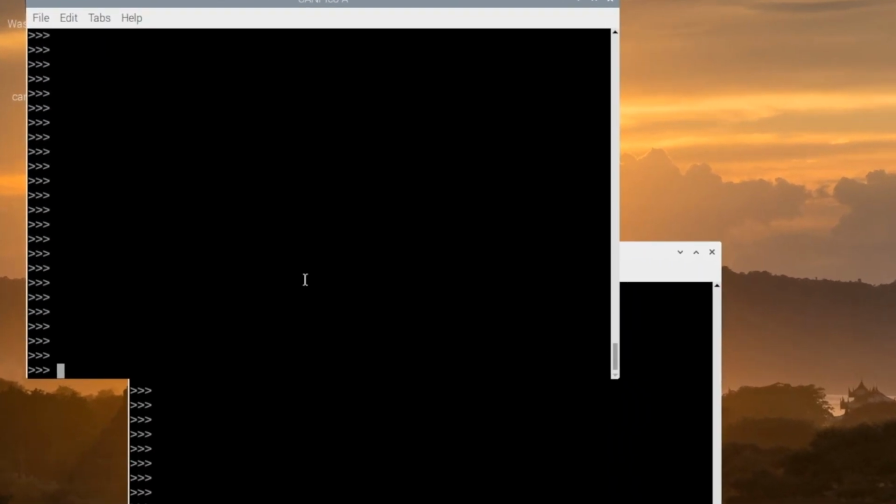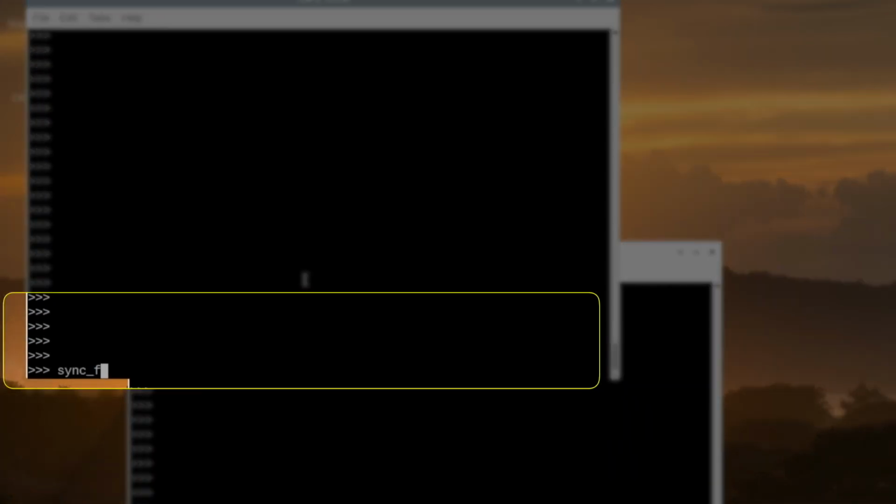So what we have is a pair of sync frames. The first sync frame is just a simple short CAN frame with ID 0, no payload. And when the other side receives that frame, it queues its own CAN frame through the drivers, and it would make its way through the driver software and eventually into the CAN controller. And then when arbitration starts, the CAN controller will enter that new frame into arbitration.